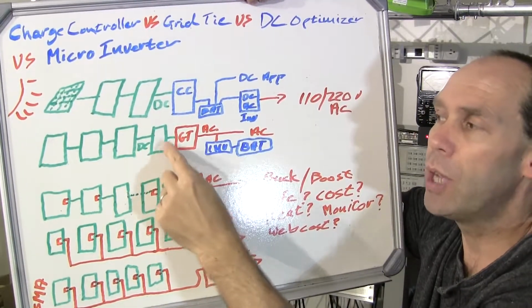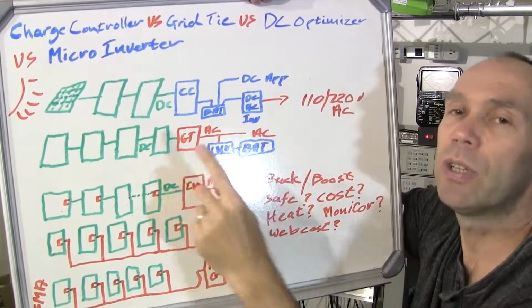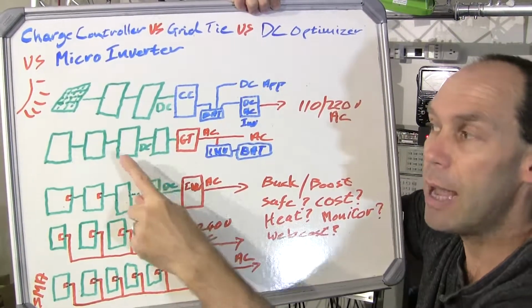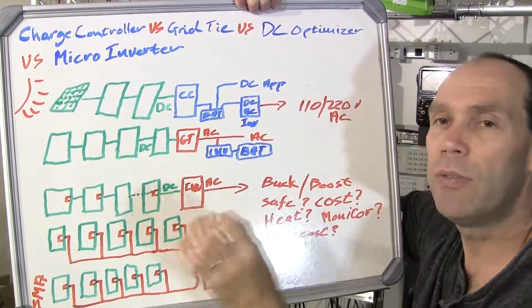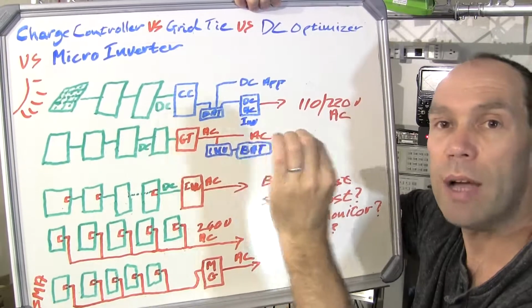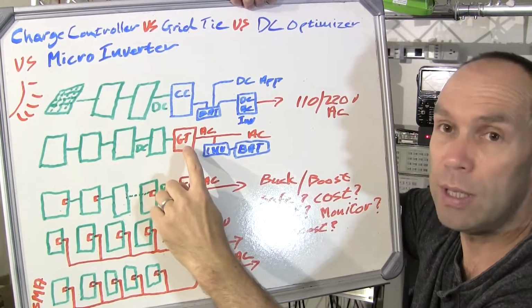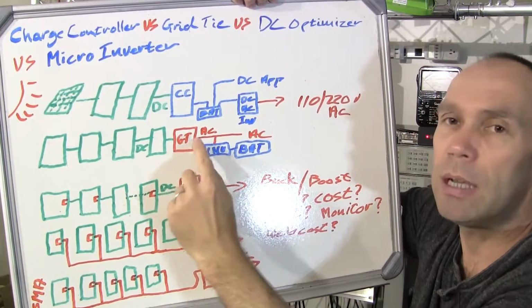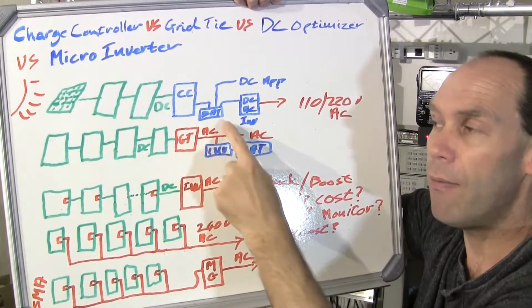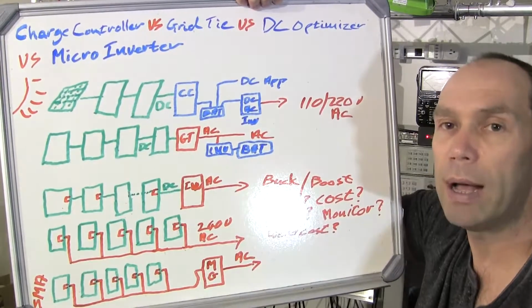The higher voltage you get coming out of that is beneficial in two regards. For one, a higher voltage means less current that has to be carried by the wires. If you have to carry a higher current through the wires, you get greater losses. Also, that higher voltage means that your grid tie inverter is going to have a better time of inverting a higher DC voltage to, let's say, the higher AC voltages that are required for households.